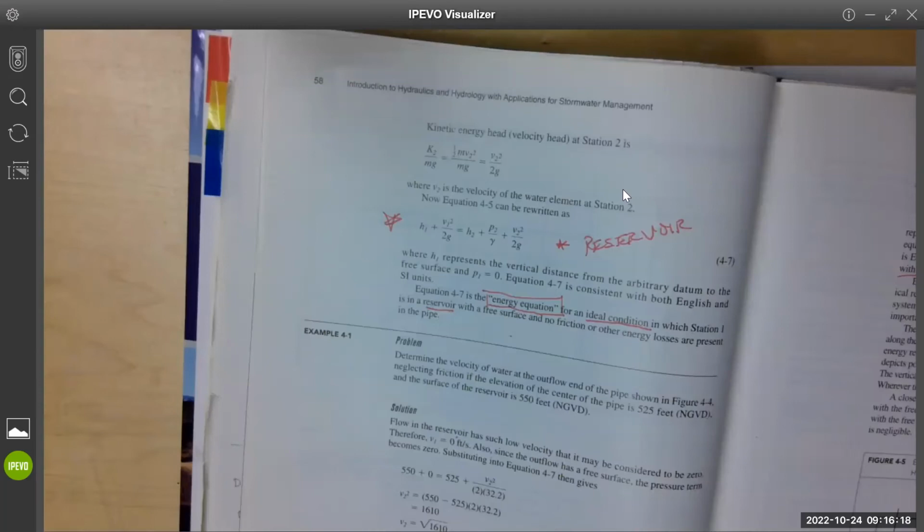You're going to just pick at parts of it, I think. So when they're asking you for the pressure head, that's this, right? If they're asking you for the potential head or the potential energy, that's this. If they're asking you for the velocity head, that's this. So these are all heads. We refer to them as heads or just pieces of energy.